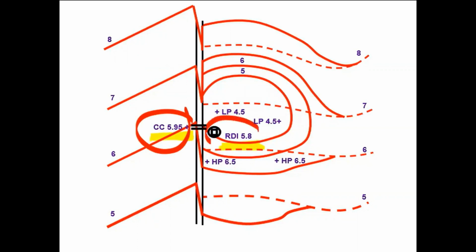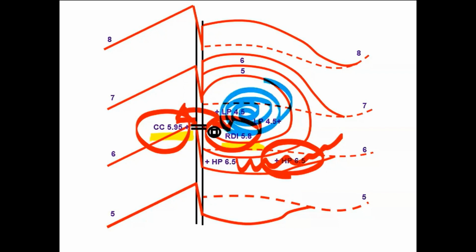The raised drop inlet is determined by two things. To begin with, it has to be lower than, at least a half a foot lower than the berm, but it also needs to be lower than the curb cut, because the idea is that as water fills up this system, the water then goes into the raised drop inlet and does not back up into the parking lot. We'll show another example where we do want to back up into the parking lot, and we may not need a raised drop inlet. But for right now, let's understand that if you're going to have a raised drop inlet,